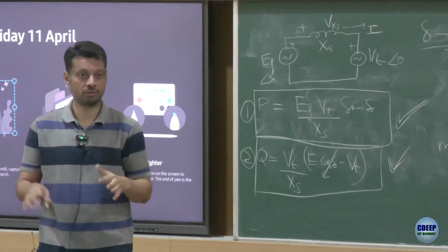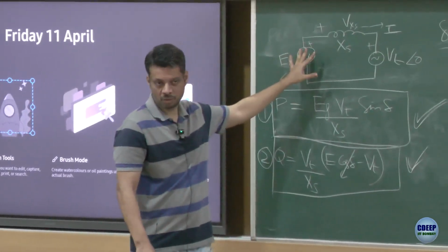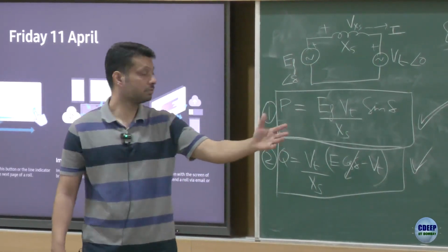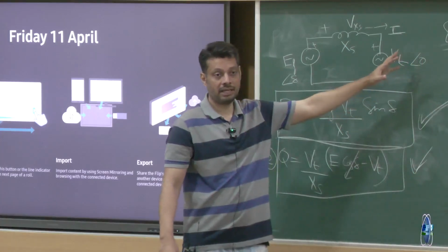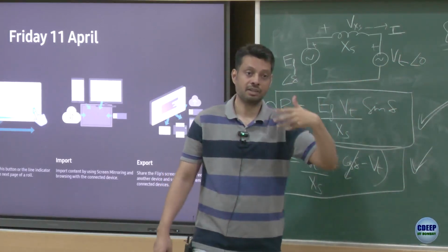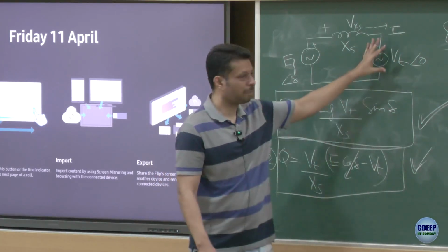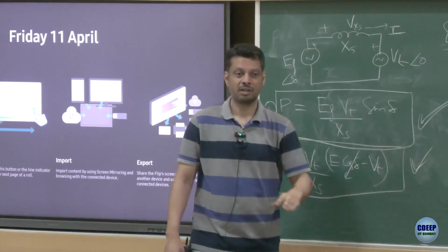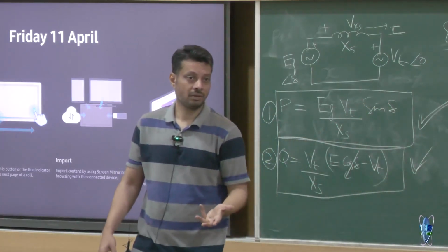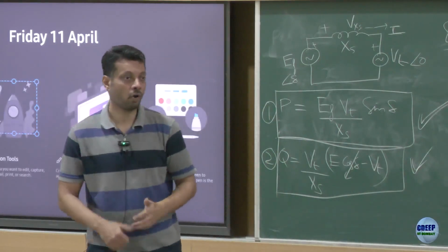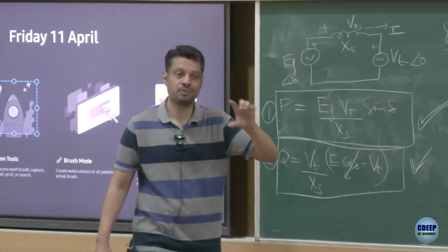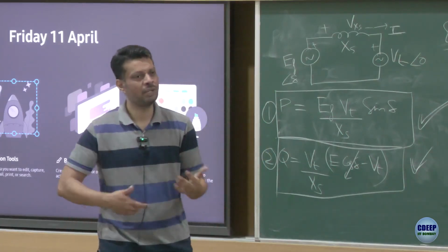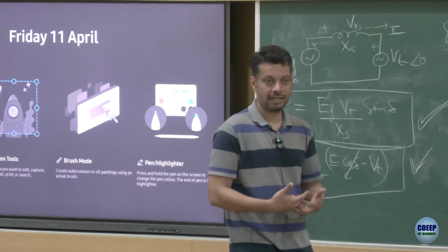If I am a source, maybe a synchronous generator, there may be a lot of inductive loads connected further, and to supply that Q, you can connect a lot of capacitors, or as a source I can produce and give that Q to them. Now you have to decide which one you want to do, whether putting capacitors is cheaper or oversizing the source and producing less P and some amount of Q is cheaper, or you usually do both, a combination of both strategies.